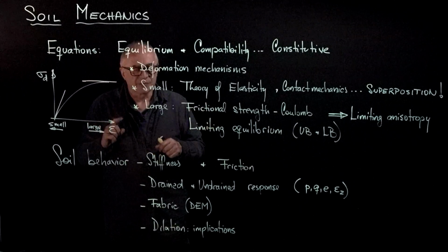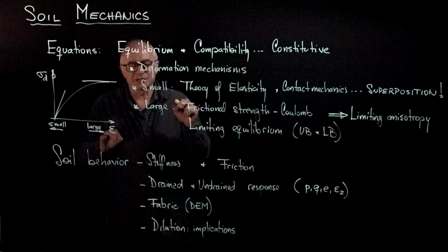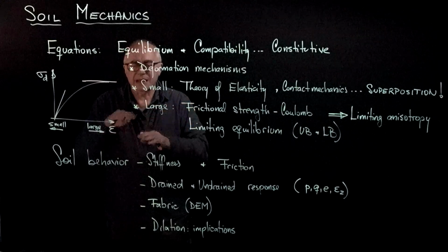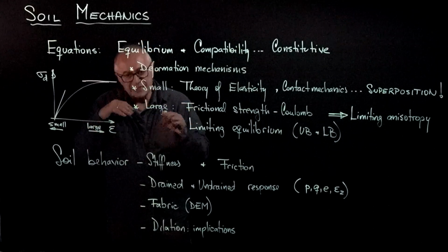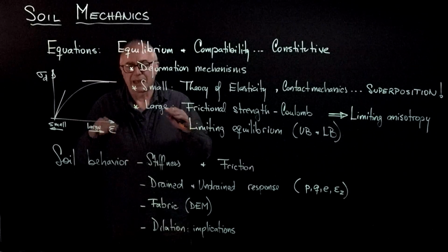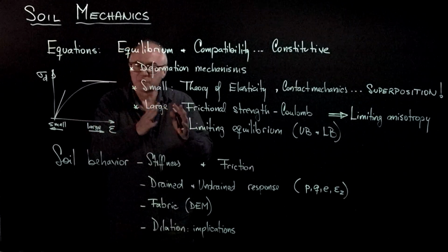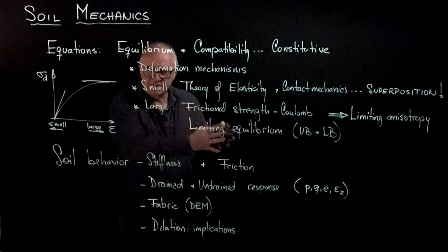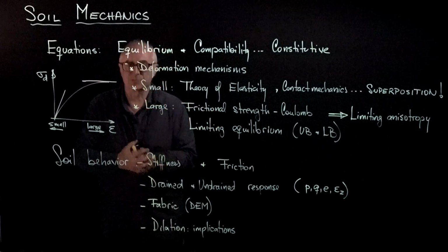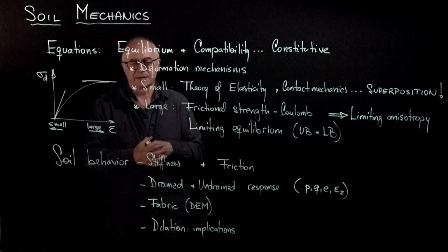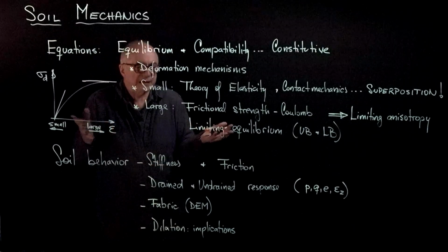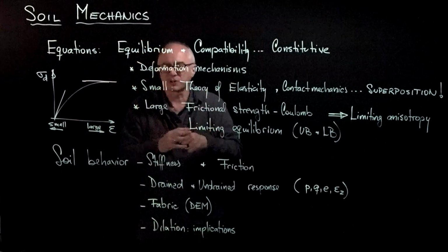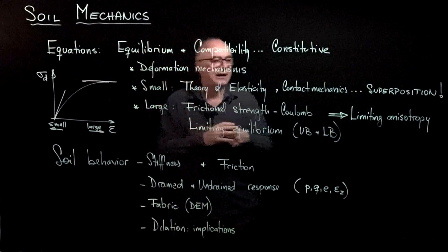Above all, because in a linear elastic regime, we can apply successive loads in any sequence of events, and the sum of the causes will produce the sum of the effects. Superposition principle applies. And so it leads to a very elegant solution. You may remember Boussinesq or Mindlin for piles, etc.